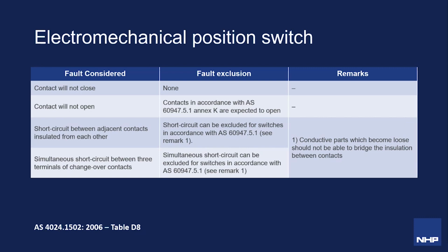On this topic of this standard, if the position switch is constructed to this standard, we can exclude the possibility of faults occurring as a result of short circuit between adjacent contacts, provided, as per the remark, that the conductive parts which become loose should not be able to bridge the insulation between contacts. This would require special construction of the terminals and proper preparation of the conductor before fixing. So, for example, appropriate stripping of the insulation, correctly sized ferrules, and so on.